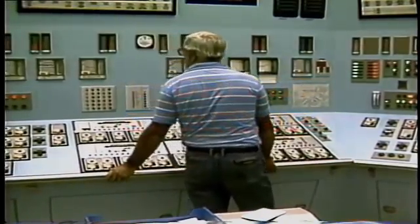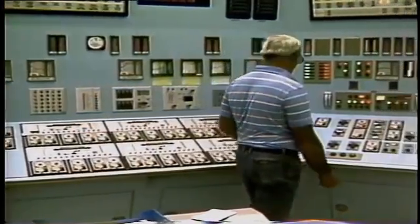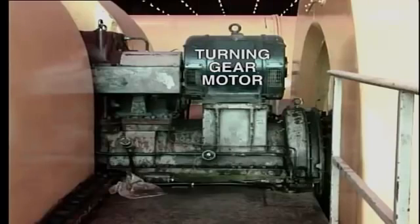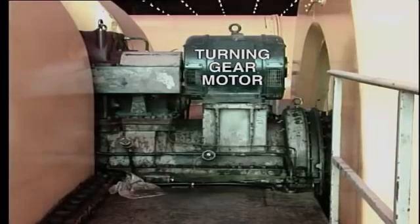In this segment, we're going to look at the actions taken by the operator to perform a typical turbine startup. Of course, we all know that there are different arrangements of turbines and control equipment, but the basic requirements for a startup are the same. Even before we think about admitting steam to the turbine, there are a number of very important maneuvers that must be carried out. If the turbine is returning to service after a long outage, then the first thing we must do is to place the unit on turning gear.